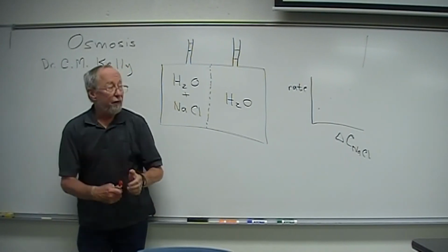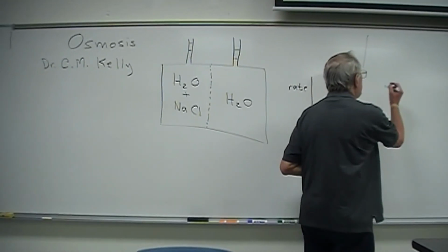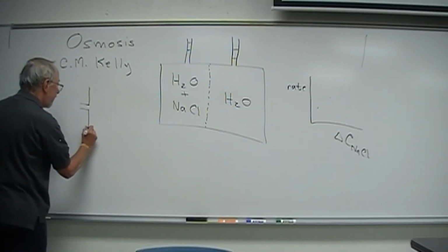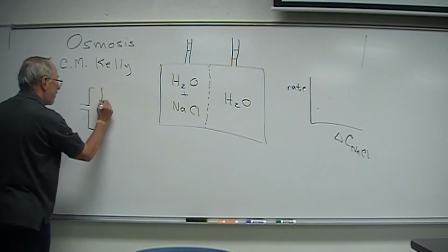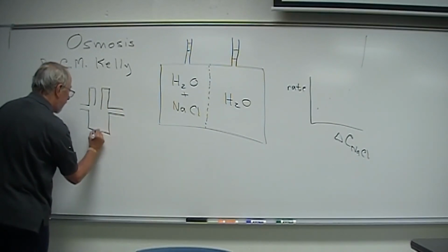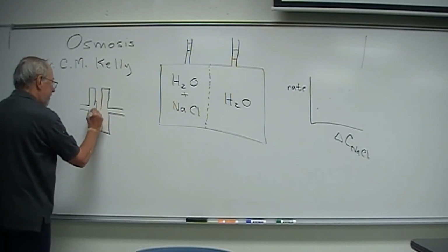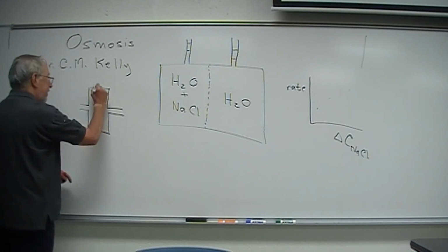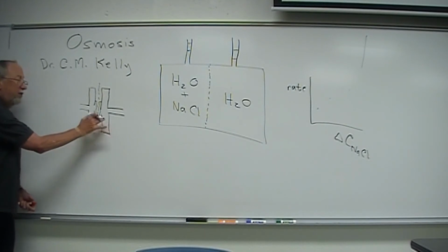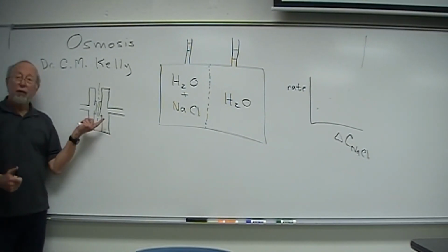Now, what you're going to have to work with is a bunch of materials that we're going to supply for you. By far, the most important single material in there is the holder for the membrane. And I'm going to put something here, like this. There will be a second plate, looking very much like this. And in between, there will be a washer on this side, a washer on that side, and then the membrane is held between them. And then there are going to be bolts to screw it down really tight so that there can be no leakage, and you'll have very good sealing.